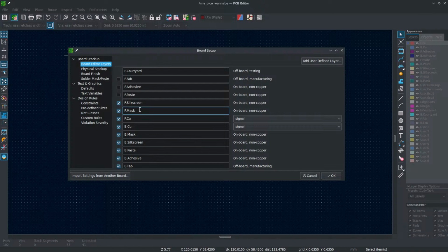So solder will bead up and not adhere to the solder mask, which prevents solder from flowing places it's not supposed to. You'll see on some really built-down-to-the-last-dollar circuit boards, they don't put solder mask on them, and I recommend avoiding those. The solder mask is a really important part of making a good assembly, so we're definitely going to leave that on.